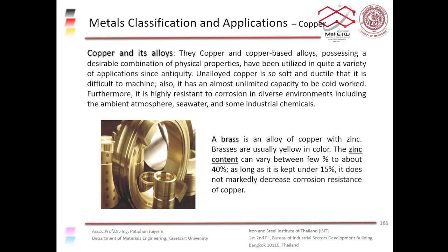Whereas when you are cold working at lower temperature, you're shaping it and increasing the strength at the same time. Because as you are cold working a workpiece, you are introducing more and more dislocations in that workpiece, making it stronger. We will talk about cold working and hot working after the midterm, in the manufacturing session.